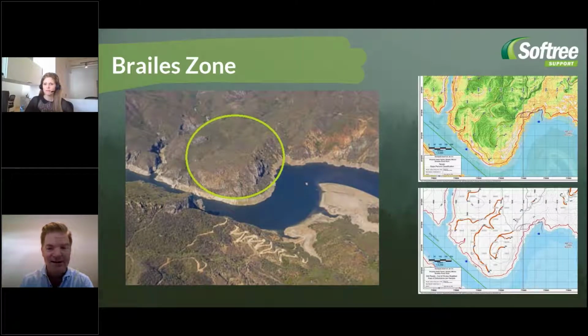And you can see there in the slide, across the river on the north side is a particularly steep area that we were doing the road design for. On the right-hand side of the slide, in green, orange, and white, is the slope classification, which, because of the high resolution, we're able to take directly into RoadEng, along with the ortho-rectified satellite imagery, so that I was able to really remotely see what was happening on the ground and do my road planning based on the slope percentage of the terrain.